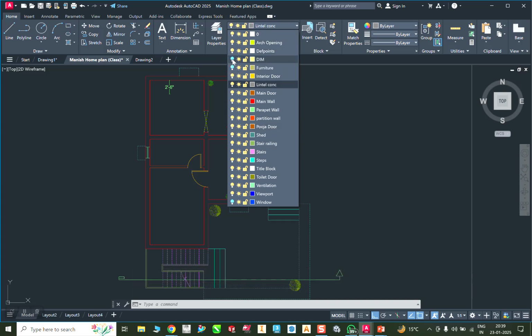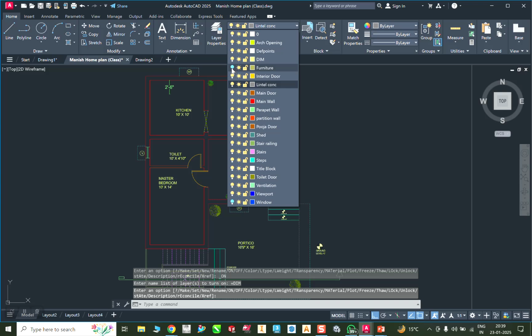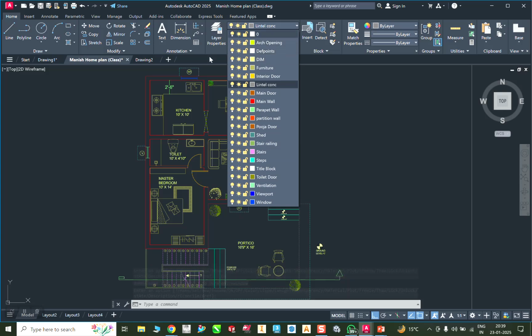So in complex plans, whatever you want to see, only that is going to be visible. If you click it back, it's going to come back. You need to just click and bring back. So that is how you turn off layers. A layer is what these colors are, whatever you have given to that particular line. When you create these lines, it is with the help of the layers. First of all I will create these layers, and then I'll make a plan. It's not that I'm just showing you what we are going to do. After that I am going to make a small plan also.